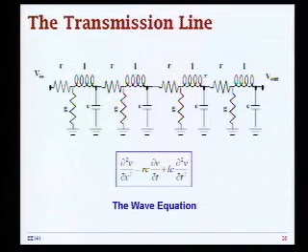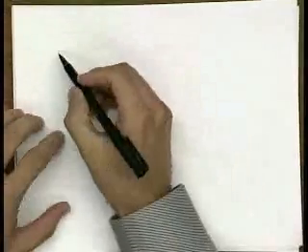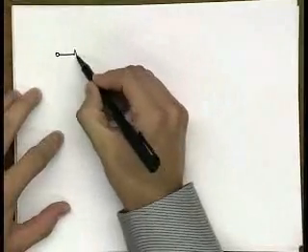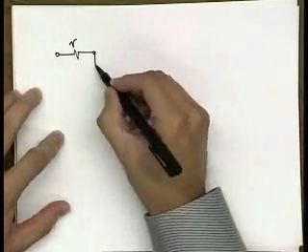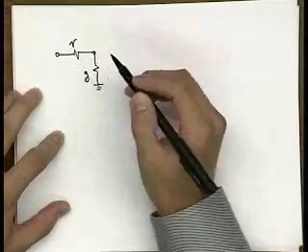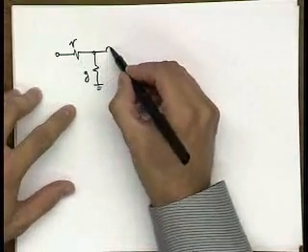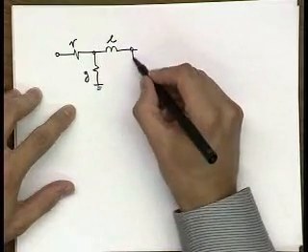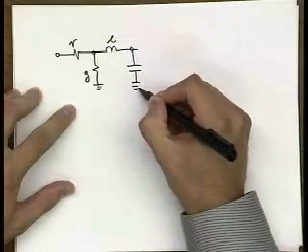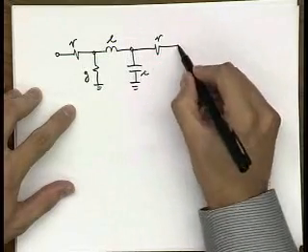And the way we model this transmission line then is, if you go to the overhead, thanks, we have a full model that includes resistance. Then we maybe also have some leakage over here, the current that goes into ground, modeled by this conductance. Then we have inductance and capacitance per unit length. And then we continue with the same model.